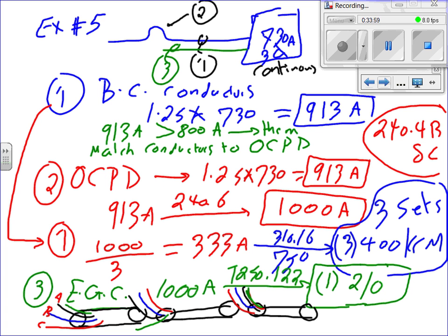These parallel conductors must be the same. If you're using 4-aught, 4-aught. If you're using copper, copper. But phase B could be a completely different size conductor, completely different conduit, completely different insulation, completely different copper or aluminum type of conductor.